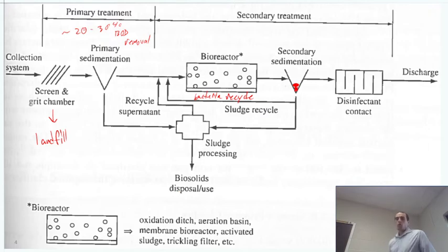Okay, secondary treatment then has the bioreactor, removal of the bacteria, which helps us recycle and keep the bioreactor going properly, and then a disinfectant dosing and discharge. So this disinfectant, if we use something like chlorine, then of course we'd have to remove it back out of the water. We'd have to quench the chlorine before discharging into nature, because chlorine is not good for fish and wildlife.